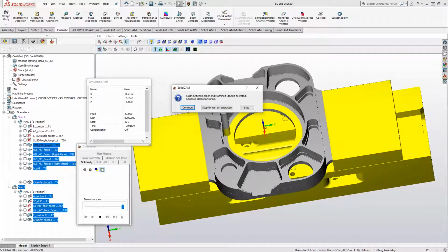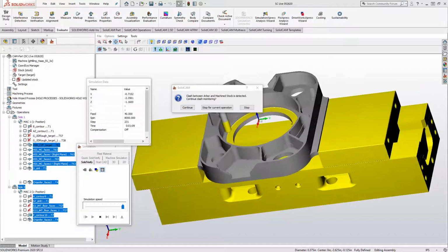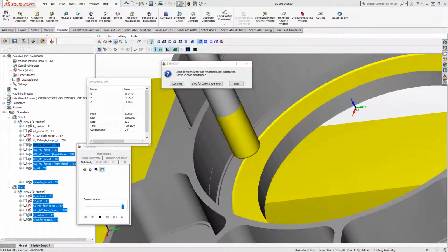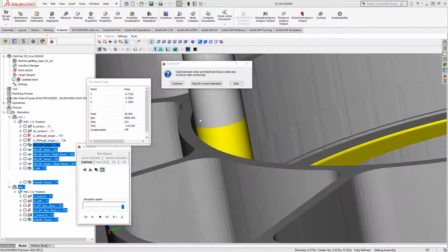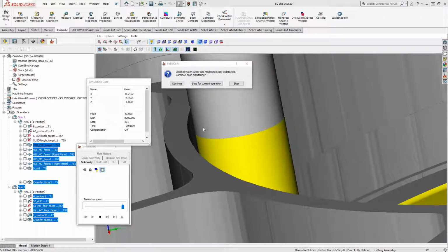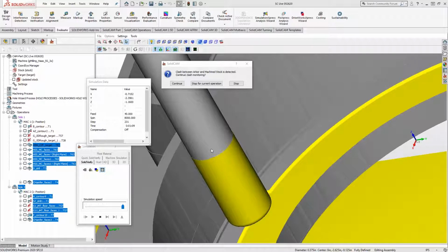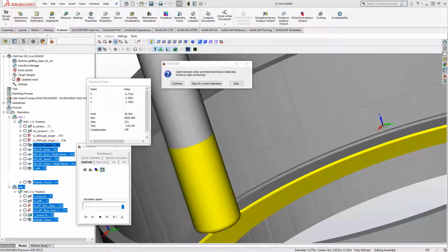And there is a warning of the arbor machine stock. That is simply because, again, if you remember, we're doing horizontal machining in our HSM. And since we didn't do the walls first, it thinks that for my tool definition, that arbor is touching. It's rubbing there, which in reality, it possibly might, or I might actually have a reduced neck here, so it's not actually touching. But I probably should have looked at that myself when we did the HSM and said, okay, I probably need to add a little bit of a step down on the walls as well. So in this case, we were trying to just do the walls at the same time as the floor.